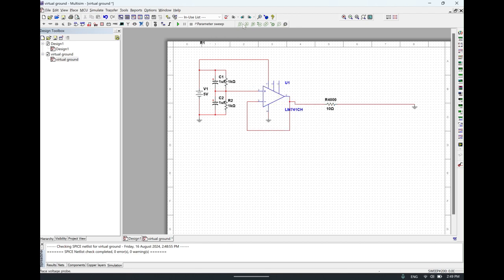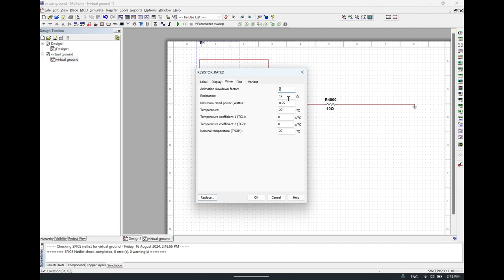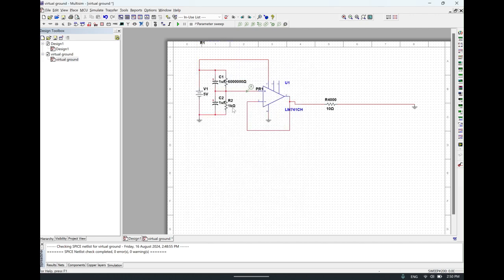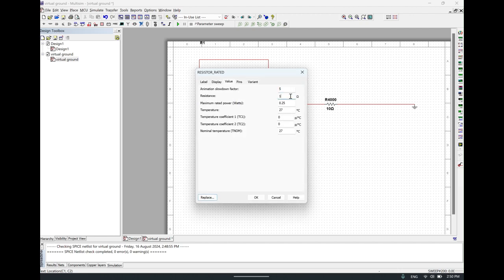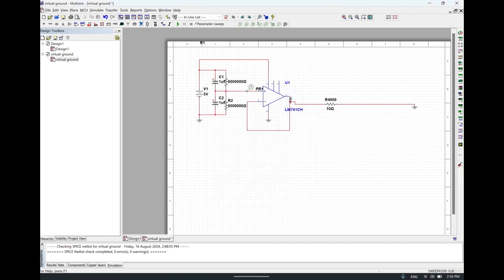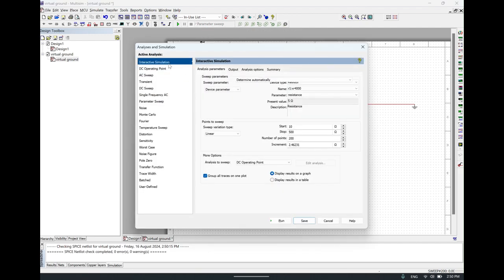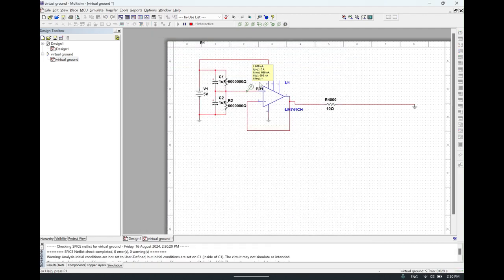Get rid of this and we'll do a current reading with 6 mega ohm. Okay, and we'll do a reading for this. See what sort of current we're getting, and it's really, really low, right at about 666 nanoamps, which is not detectable with a traditional voltmeter.